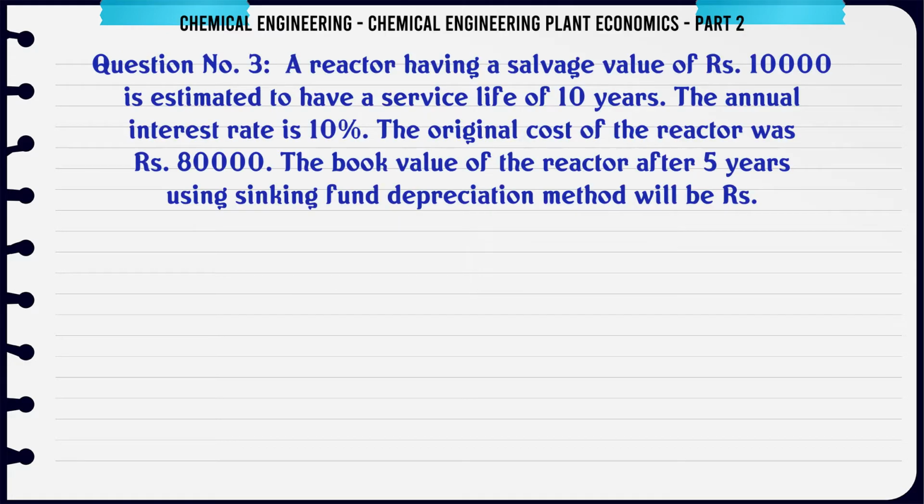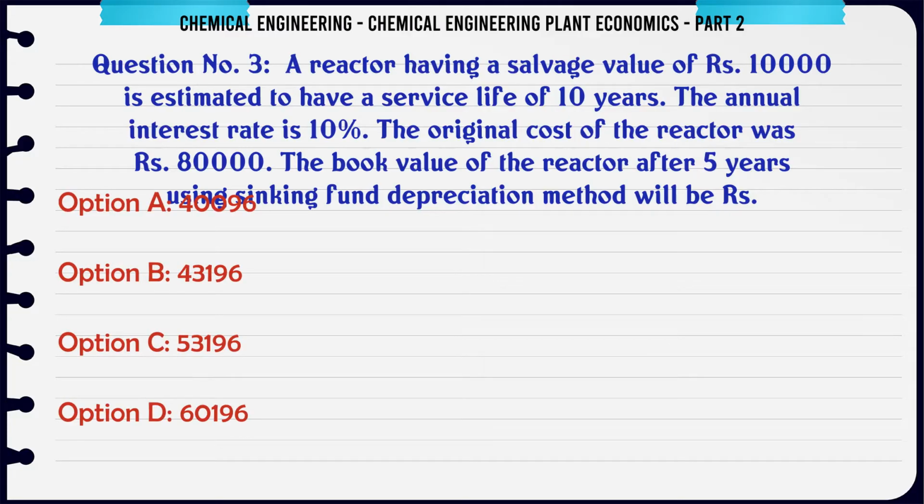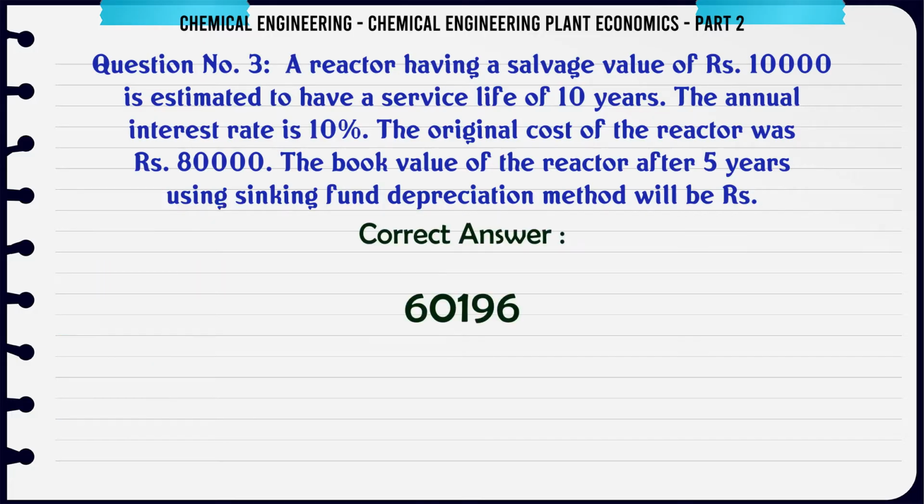A reactor having a salvage value of $10,000 is estimated to have a service life of 10 years. The annual interest rate is 10%. The original cost of the reactor was $80,000. The book value of the reactor after 5 years using the sinking fund depreciation method will be Rs. A. 40,096. B. 43,196. C. 53,196. D. 60,196. The correct answer is